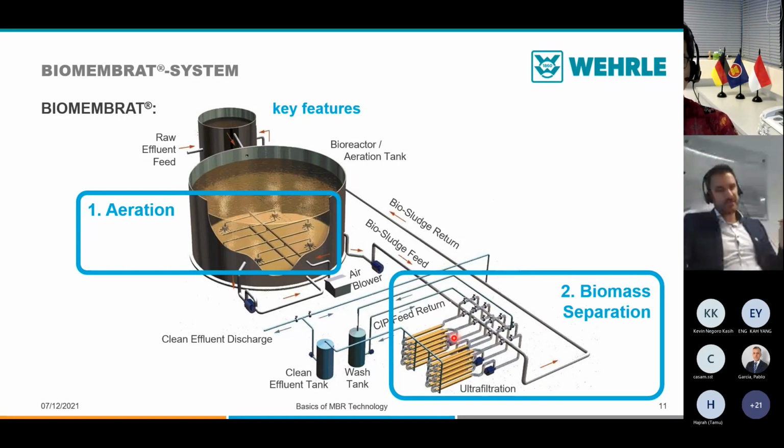Therefore, we have external membranes with booster pumps, where we are pumping the sludge through the membranes with a speed of around 3 to 4 meters per second, which means all the COD and BOD particles cannot sit on the membrane, the scaling material cannot sit on the membrane, so that we have a cleaner membrane. This is one big advantage.